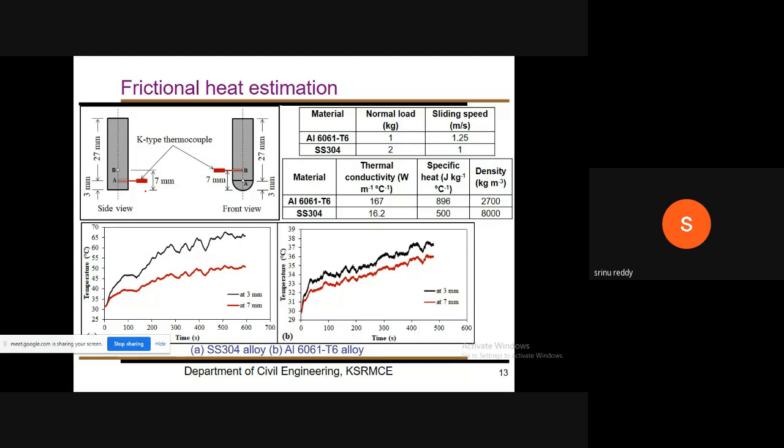In this pin, if you see in different directions, one direction looks like a flat contact, but that is not flat, it is a line contact. The other direction looks like a cylinder contact. Here you can see this curvature easily. On one side, we were unable to arrange these thermocouples in one phase. That's why in two perpendicular phases, we arranged one thermocouple at 3 mm and one at 7 mm, as you can see here.